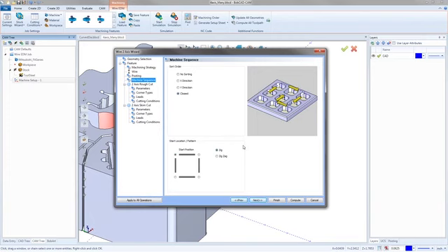Right here's the machine sequencing. This is really only going to be used if you're doing multiple cuts. And on this part, we could do a few different cuts at the same time. But in this case, we really don't need to change anything. It's just how you sort it. One note, you got X direction, you got Y direction, you got closest. They all make sense. Those should just work pretty naturally. The no sorting one is the one that throws most people off because it's no sorting. It's just going to jump randomly.